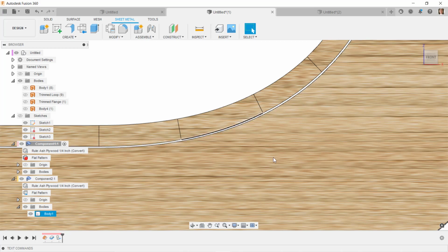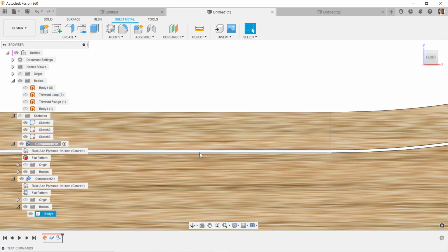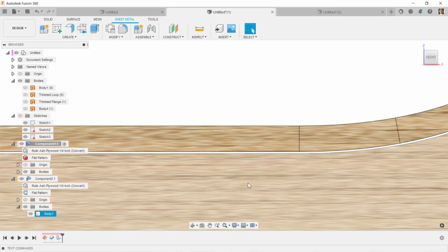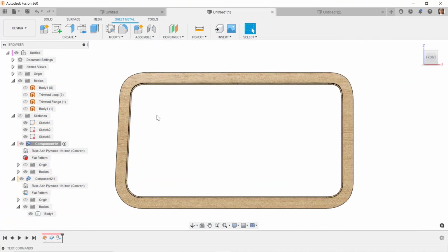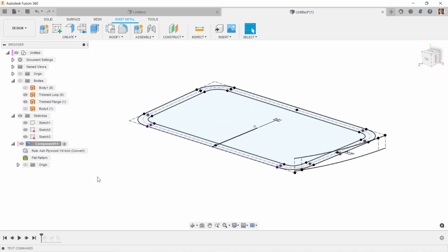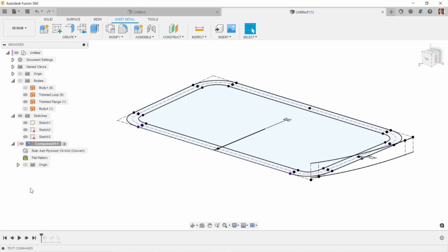Now for the amount of that gap that you put in there, you would have to determine how big of a gap to put in there based on your manufacturing experience, understanding that we cannot make absolutely perfect parts. So really the perfect part is to include realistic clearances between components based on our manufacturing tolerances in our assembly process. And I need to go a couple more steps here till I have that.